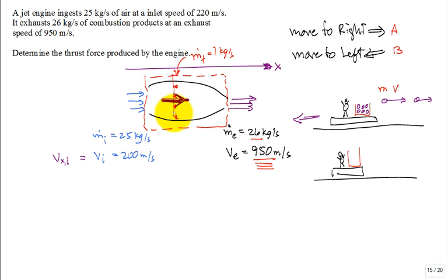So if I put that under a wing of an aircraft, here's my wing of my aircraft, the wing of the aircraft is going to feel a force in the opposite direction, of equal magnitude. And we're going to call that the thrust force. The bottom of the wing feels the thrust force when that engine's running. True? But the way we calculate the thrust force is we consider what's necessary to hold the thing stationary. And it's in the opposite direction of what the wing would feel.